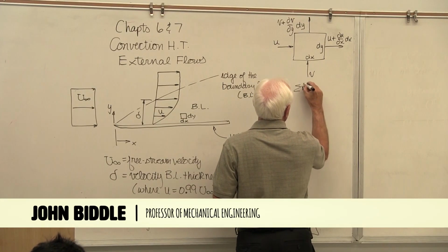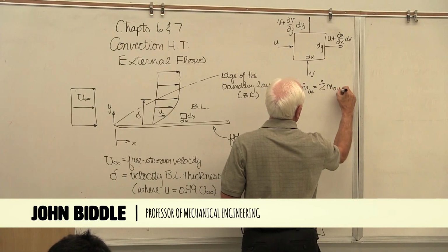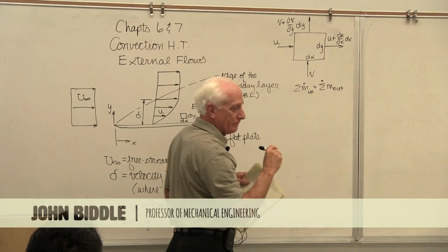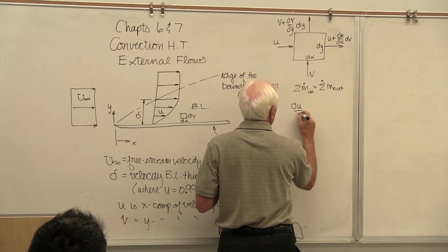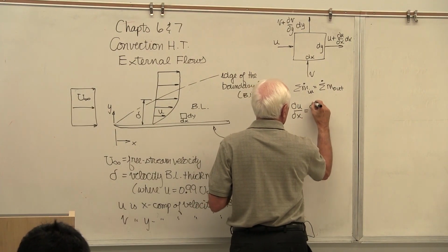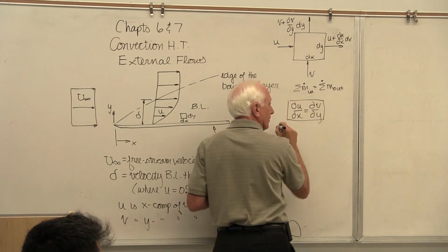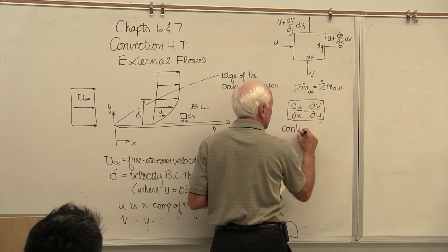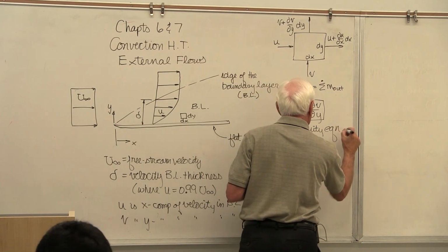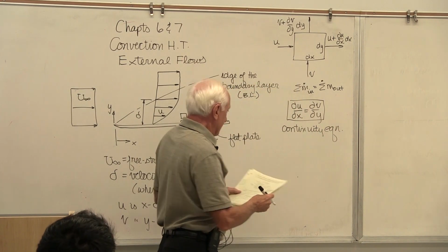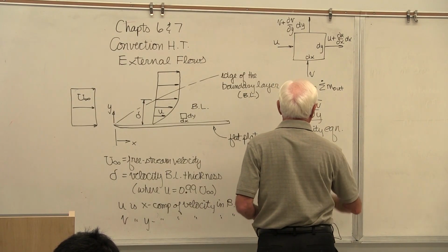Summation of the m dots in equals summation of the m dots coming out. No storage, steady state. We end up with partial u with respect to x equal partial v with respect to y. And that's the differential continuity equation. Equals 0, plus equals 0.